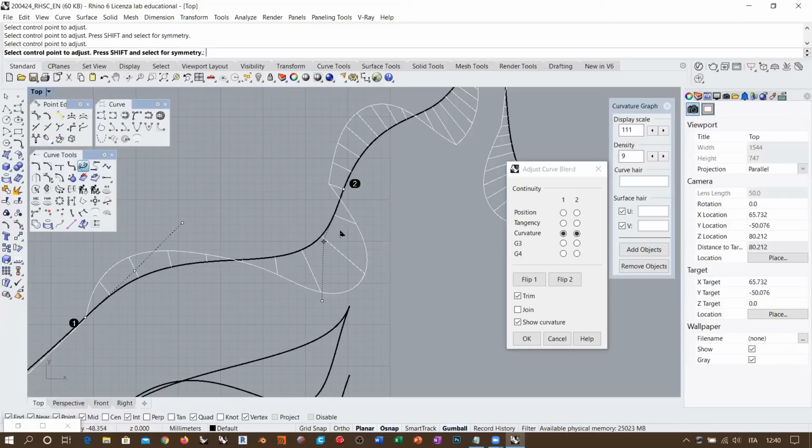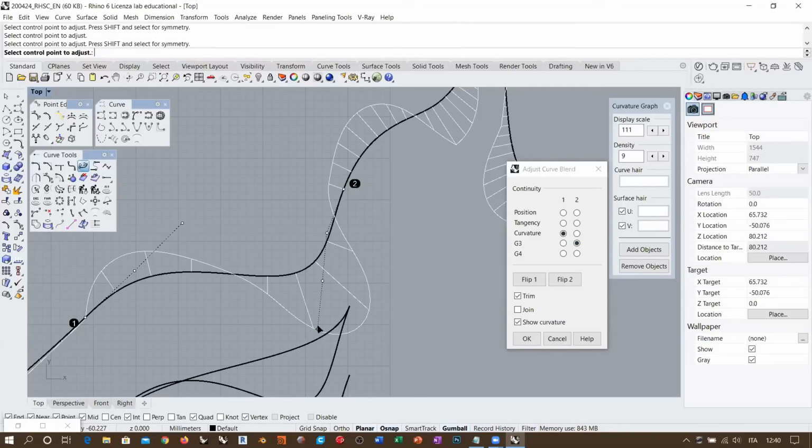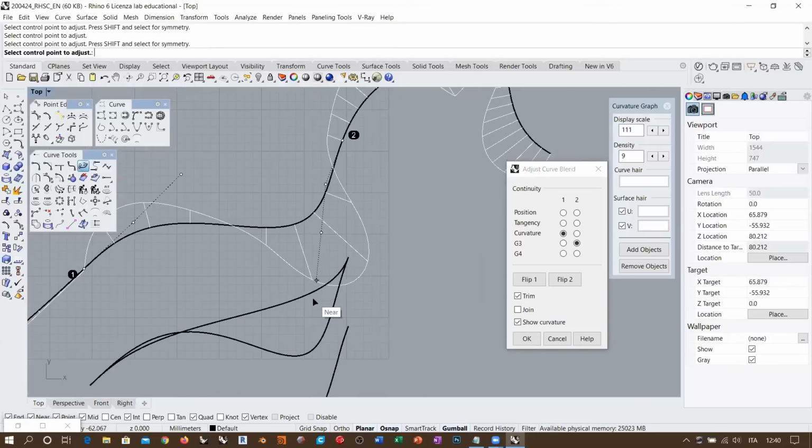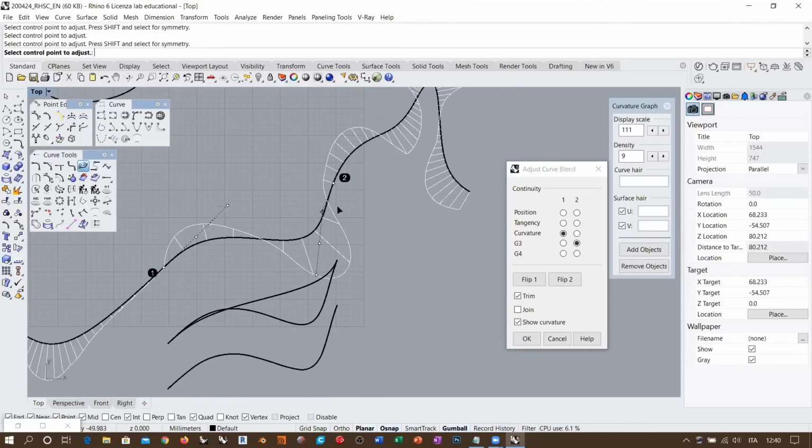This will be a visible curvature, well, not discontinuity, but variation, right? So in order to avoid this, if I set this to G3, an additional control point is added, which is in this case aligned along the direction, and this avoids a correction in the direction of the curve. So it avoids oscillation, right?